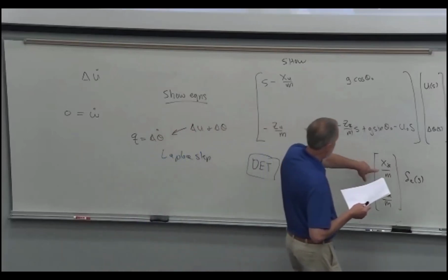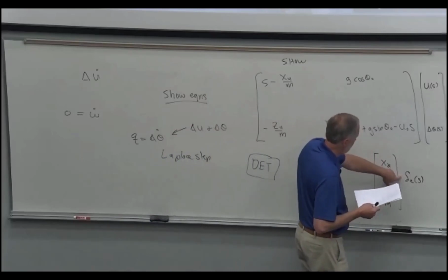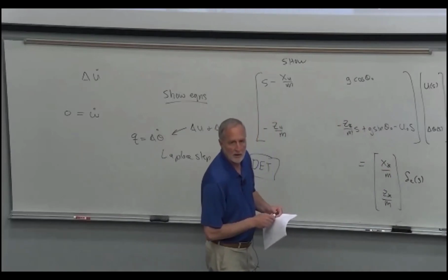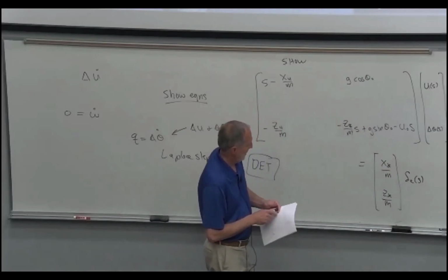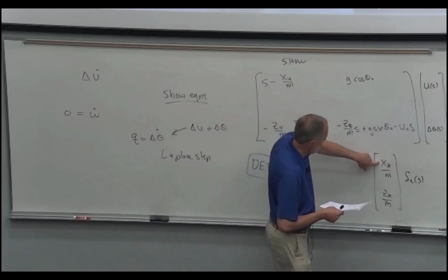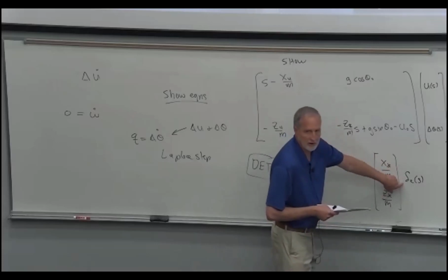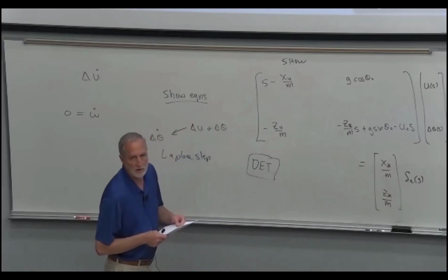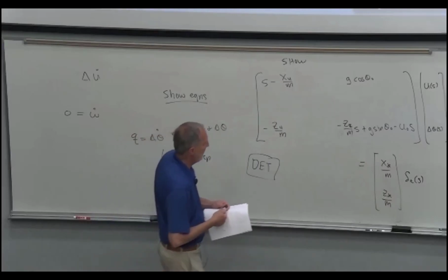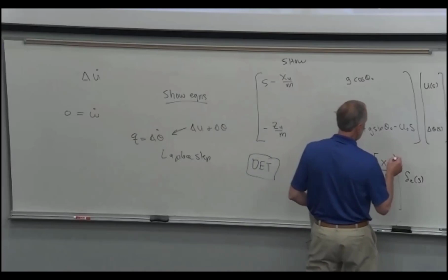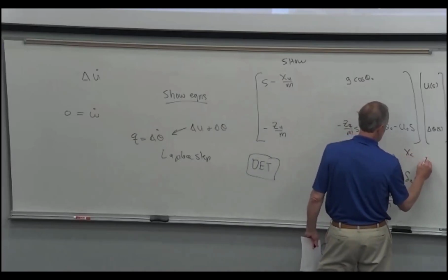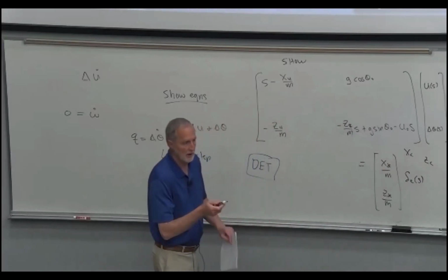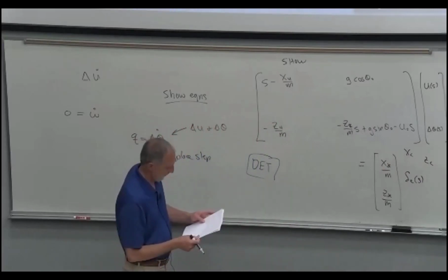Well, no, the control is x delta E times delta E. So that's what we're calling x sub c. Right, so this is the drag due to the elevator, and this is the lift due to the elevator, is really what it is. But I'm okay with you just put, because initially in the equations they put x sub c and z sub c that contain both of those. Is that okay? Okay.